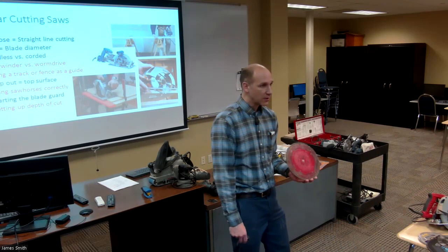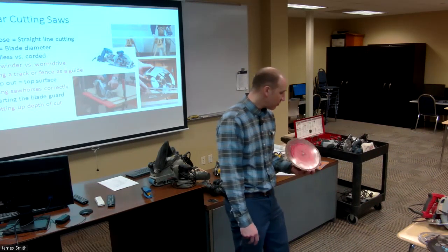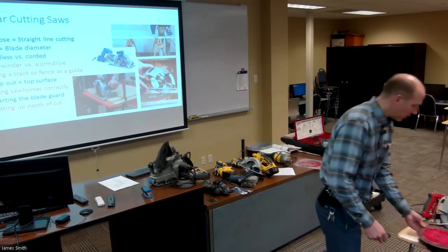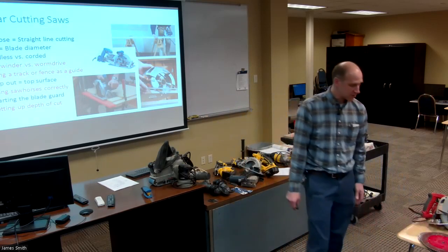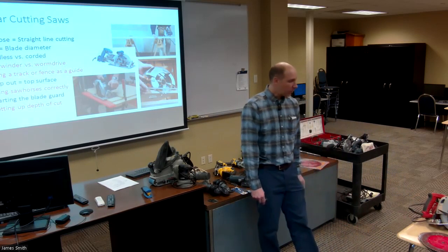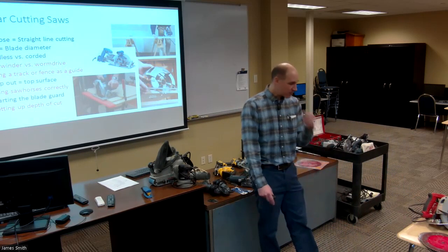One or two is not a big deal, but if you get too many of them, that's usually another reason why they put on there not worth sharpening. It's best to just go buy a new one. Just to give you an idea, a new blade, a good one, will be around $60 to $70. A 10-inch blade, I'm talking.